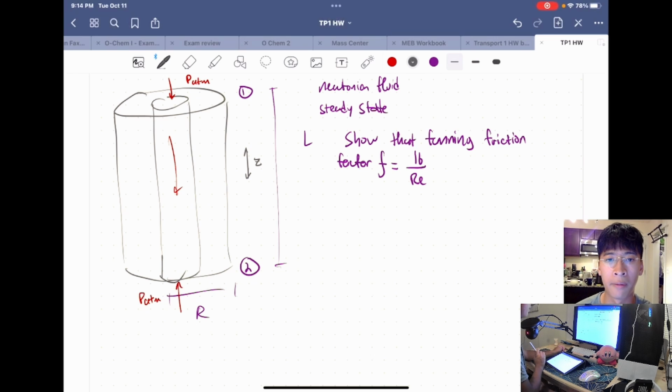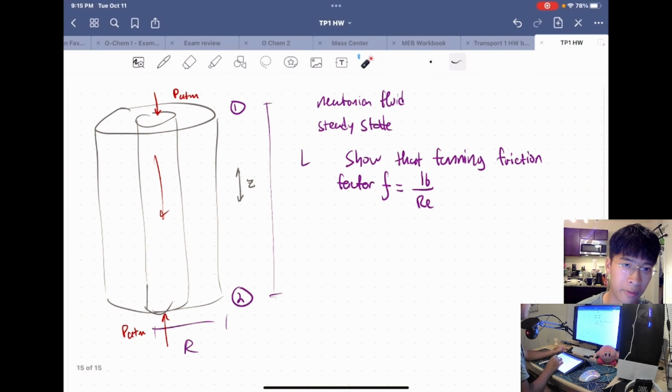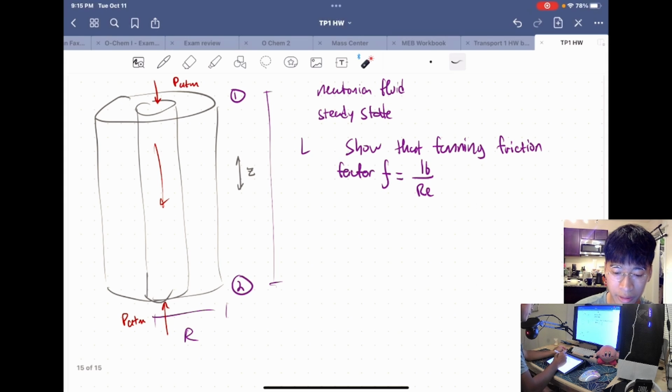We're going to start off by taking a look at a force balance, okay? And the force balance goes like this. We first consider our pressure forces, and we realize that, hey, the pressure at position 1 and position 2, it's both atmospheric pressure, okay? So therefore, the pressure forces are both the same. What does that tell you? That tells you that there's not going to be any pressure recovery here because there's no increase in pressure down the line. Okay, what else do you know?